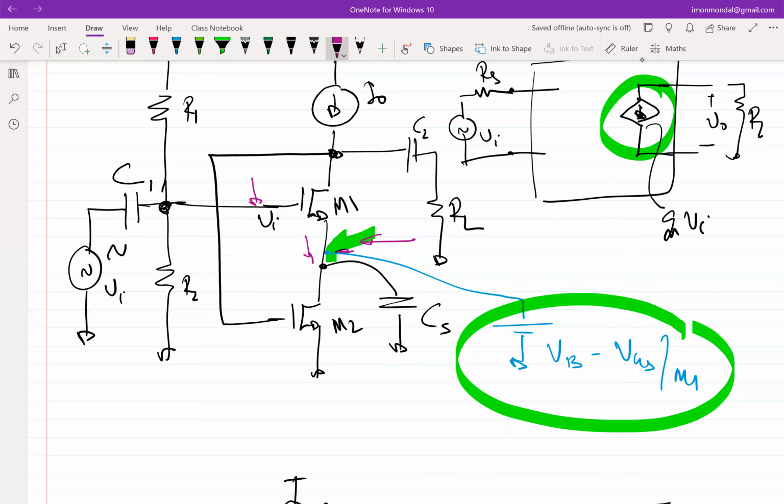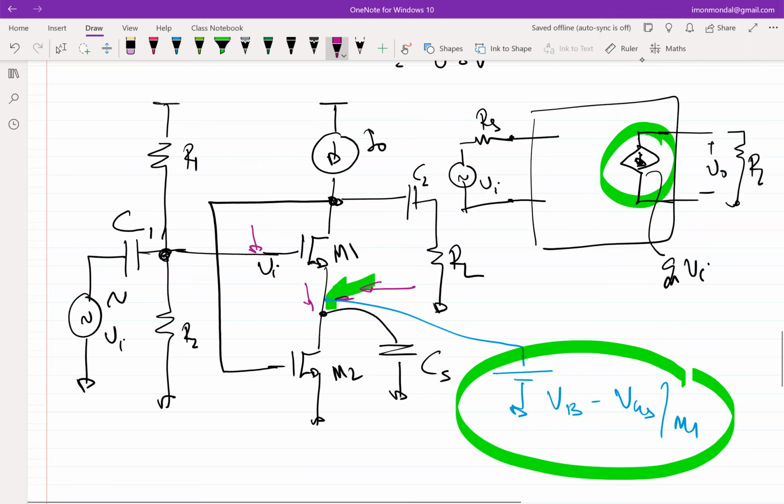Sir, is this circuit very much resilient to supply voltage change compared to? We haven't really gotten into supply voltage change now. If you have a constant current source, and if you assume this current source is constant across everything, then it doesn't matter, right? Whatever you do across the supply, it doesn't. Because in the previous analysis, you showed that the base voltage changes at a certain rate, then the V out does not change. The Q point remains. Correct. So in that sense, I'm saying that if the supply voltage changes.